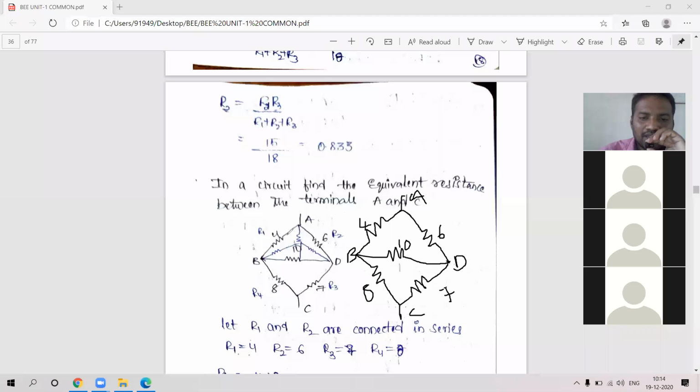Here the logic is given. Either you can take the logic that the above circuit is delta only, or the below one is also delta. You just apply it anywhere: make this delta into star, so that the outer elements, the 3 resistors 4, 6, 10, are replaced by the star connection and will not appear again. The remaining new circuit is what you are going to get.